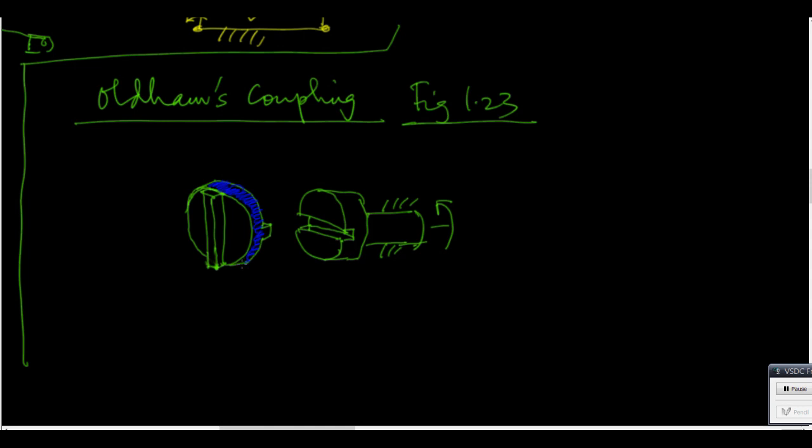That's the side edge of the disc. And then using pink, let me indicate this one is a key. It is horizontal in the present configuration. Of course, everything will rotate. And this is another key that is vertical. This horizontal key fits in this horizontal slot. When it rotates, this disc rotates along with it.